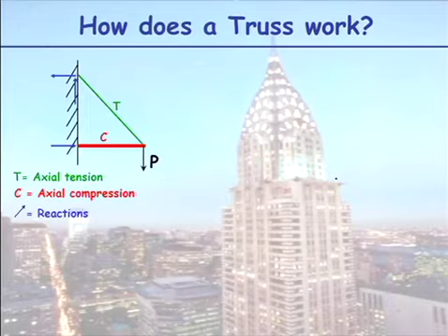So if you think about how a truss works, here's the very simplest type of truss, just 2 members connected up to a wall. Can you imagine here when we pull down with this force P, I don't think of tension compression forces. I ask myself what's stretching, what's squashing. So when you pull down with this force P, I think you can all imagine that this thing wants to move down. So you can see our green member is in tension, it's stretching.